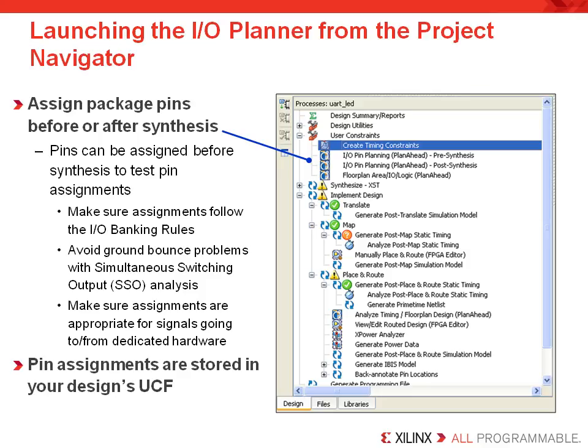This is used to make certain that each of the I/O banks and their associated pins do not run the risk of creating a ground bounce problem. This can sometimes occur if you exceed the device specifications for the maximum number of I/O pins per I/O standard in a bank. The noise analysis tool is disabled when launched from ISE. It can be fully utilized when an I/O pin planning project created in the standalone version of PlanAhead is used.